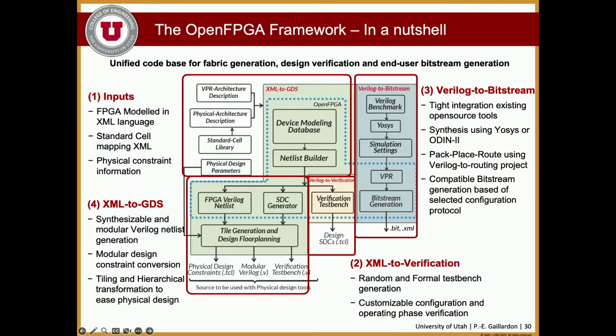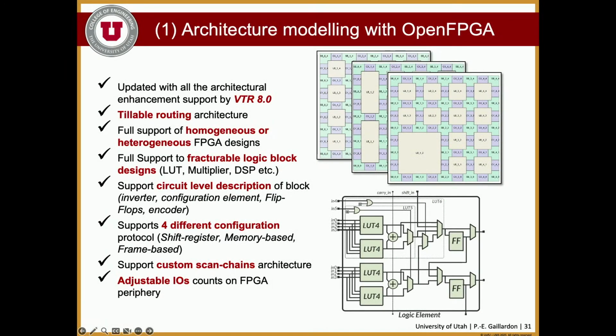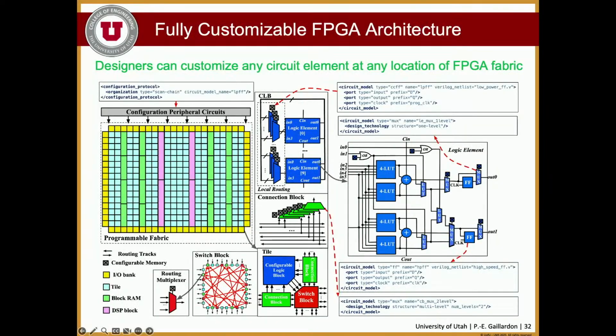Essentially, OpenFPGA supports a very wide set of different topologies, from very complex, very modern types of topology. You'll recognize some types of structures I showed earlier in the presentation. I'll pass on the details of everything it supports, but in principle, here it is. You have your FPGA array and your different blocks. Again, you recognize some sort of modern logic block. And what we do is use this high-level language to describe what we have. So for example, right here, we say this multiplexer that you use to select between your flip-flops, so your sequential and combinational path, I showed that earlier.